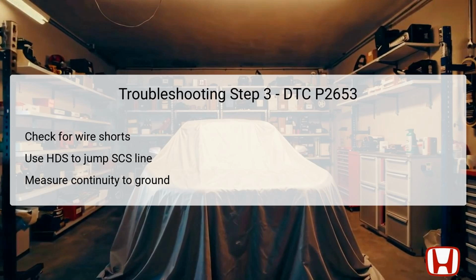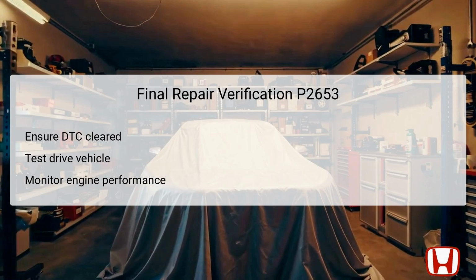After completing the troubleshooting steps for DTC P2653, it is crucial to verify that the repairs have been successful. Start by ensuring that any previously recorded DTCs have been cleared from the system using the HDS. Following this, a test drive is necessary to assess the operation of the vehicle under normal driving conditions.